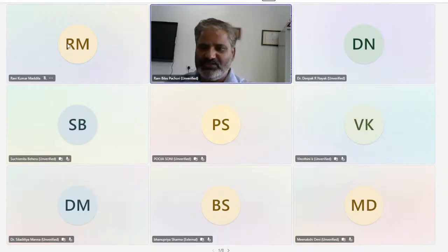See, one of the major differences between the conventional wavelet transform and whatever I have presented today is that biomedical signals and images are unknown. We don't forcefully represent them in terms of wavelets or sinusoidal functions. Here, whatever basis functions you obtain, the IMFs, are part of the signal or image itself. So it is an adaptive, data-driven approach. The wavelet approach is data independent: whatever image or signal is coming, the basis functions are fixed.